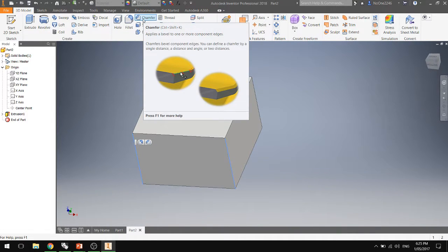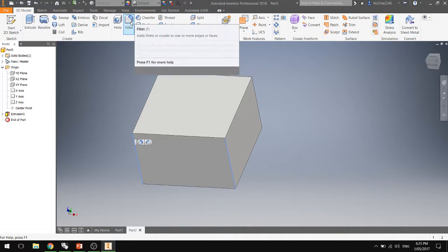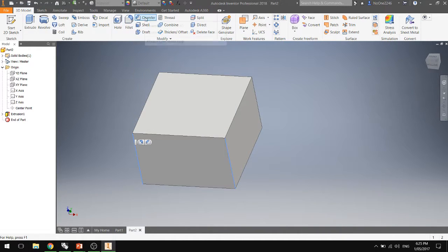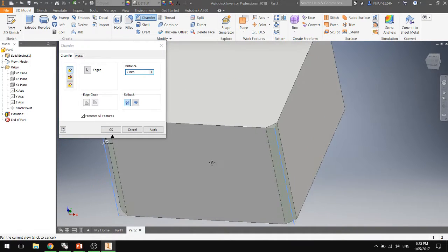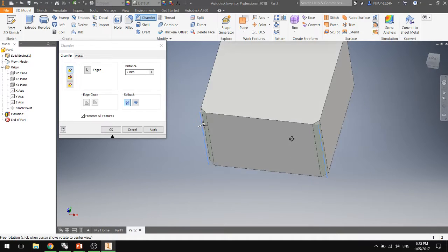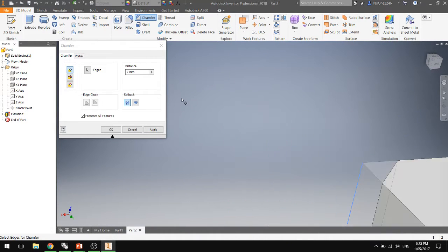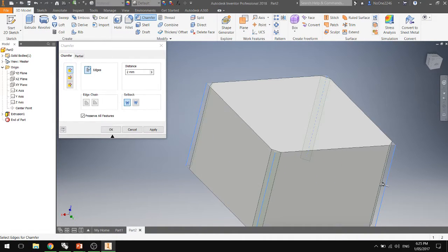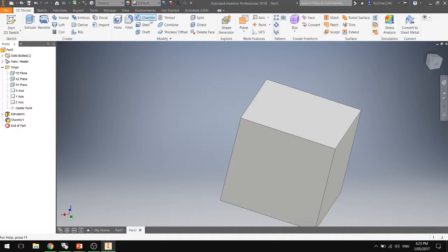Yeah, okay. And then up here you'll see the chamfer tool. Rather than making them triangular, you can use an actual fillet, which is a radius rounded edge. But for now, let's just do chamfer. The two that I've selected are already done, but I'll add in the others as well. There you go. There's lots of options for this as well. Everything has options. It's crazy, but let's just do, say, 10 millimeters, if that might be too much. 20. No, that results in an error. Yeah, that was way too big.